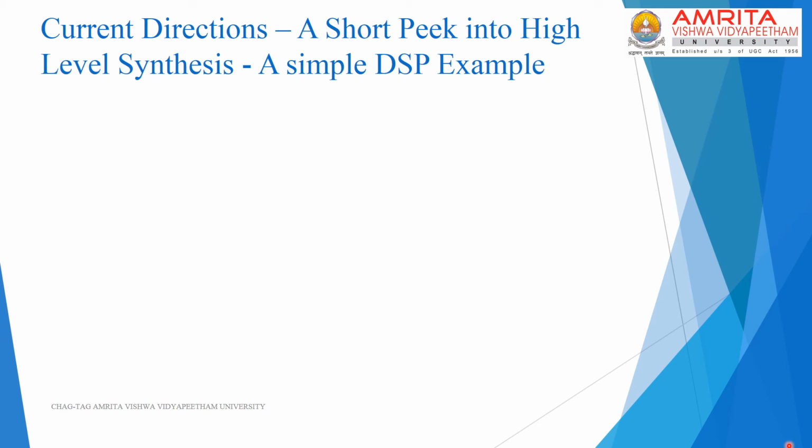So I have taken up a very simple, trivial example of a DSP filter. So we all know that filters are represented by difference equations, which can take the simple form that is shown here. So this is an algorithmic description that may be provided in C or using a MATLAB code. Now in a typical high-level synthesis flow, the high-level synthesizer will parse this algorithmic description and it will translate it into an intermediate stage called a data flow graph.